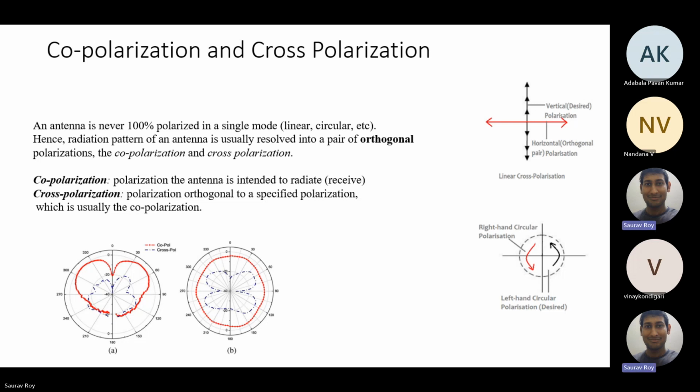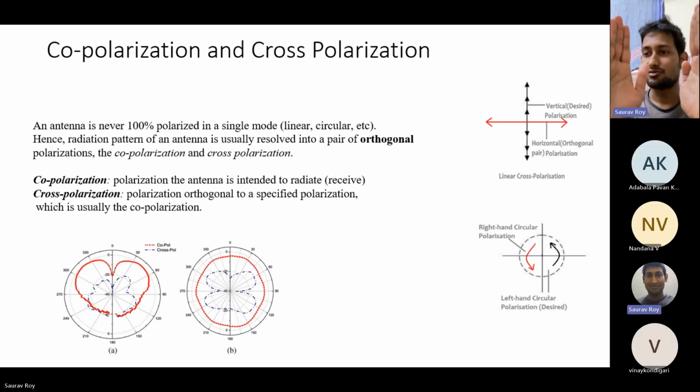In a practical measurement, what we do is that we take two planes. One is the E plane, another is the H plane. That is what we measure. Let me switch on my video once again and see. These are the two antennas. So why two antennas? In our measurement setup, we will always have one antenna fixed. This is our reference antenna.